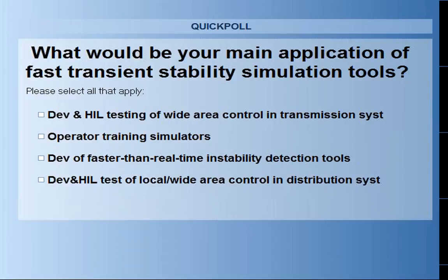When you want to perform a simulation with a higher time definition, you can count on our solutions such as HyperSim and eMegaSim, where you can simulate electromagnetic transient phenomena with time steps in the range of microseconds. And furthermore, for those who have a need to simulate power electronics with very high time definition, RT-LAB also offers the FPGA Sim solution, in which the time step can go as low as tens of nanoseconds.